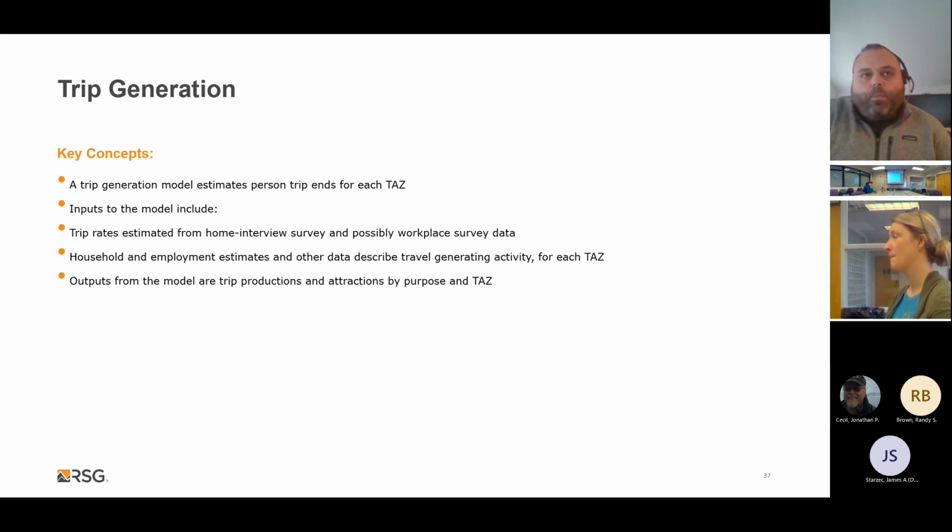So we're not looking at when someone chooses which mode to take. And there's debate on where mode choice should actually fall in the steps within the industry. There are examples of mode choice models where you choose your mode before you choose your destination. That's one logical consideration that's accounted for in other models. For example, at my MPO, we always modeled mode choice before we did trip distribution. So in our area, we thought that people were choosing their mode first, choosing how they're going to get somewhere, and then once they've decided what mode they've chosen, they decide where they can travel to based off the mode that they've chosen.